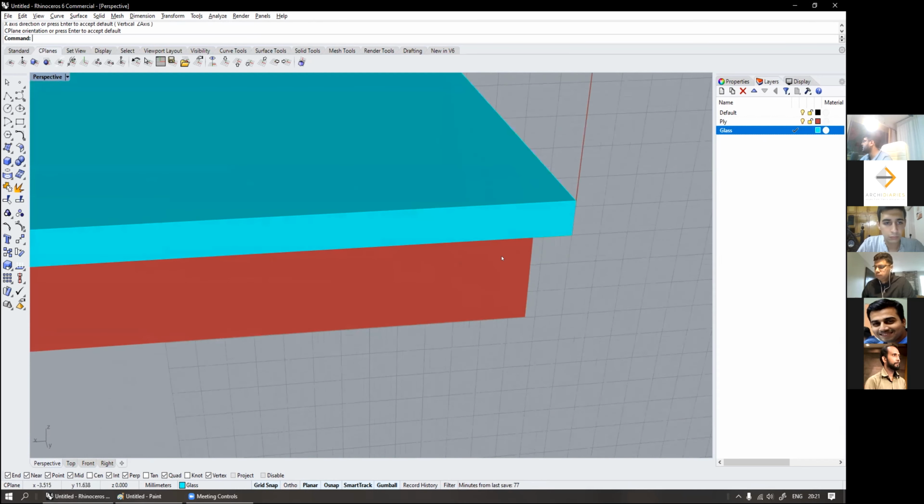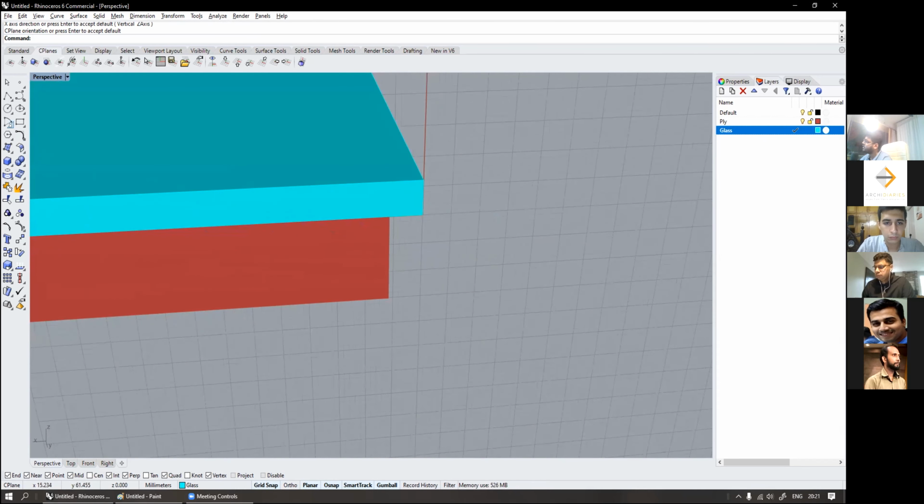What I'll do is create an arc. In order to create an arc, you use this option over here, and there is a drop down over here, and I'll select this one: Start, end, and direction. So I'll create an arc like this. Is this good with everyone? Yes or no?